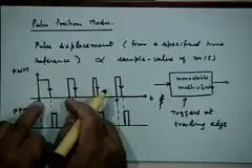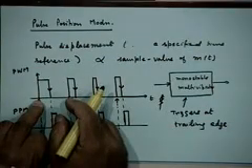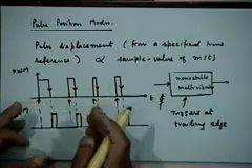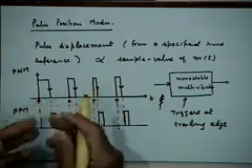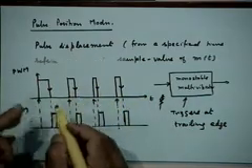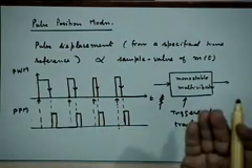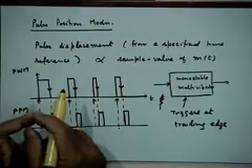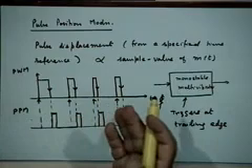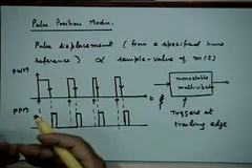Suppose within this duration you want to transmit many more signals. Then obviously there is a limit even to the pulse width you can have for an individual signal. See, this 1/2 fs maximum width I talked about was when you are transmitting only one signal. Suppose you are transmitting 10 signals, then the maximum pulse width you can have is 1/20 fs, because the second signal will also take its range of pulse widths. So the pulse width that you will end up using will finally be dictated by the number of signals you want to multiplex in time.